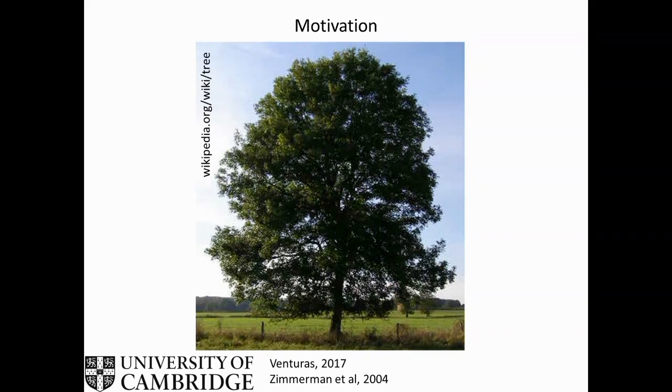The biologists, as one can read, for example, in this very recent review, say that the water in the tree is metastable, and therefore the water column doesn't break when we exceed the cavitation threshold, when the pressure becomes larger than approximately 1 bar. However, not everybody likes that idea. Particularly in dams, the idea is relatively unpopular, and most engineers have issues with the notion of water being metastable at extremely low pressures. So roughly every 20 years, somebody, like the last one was Zimmerman in 2004, attacks this view,